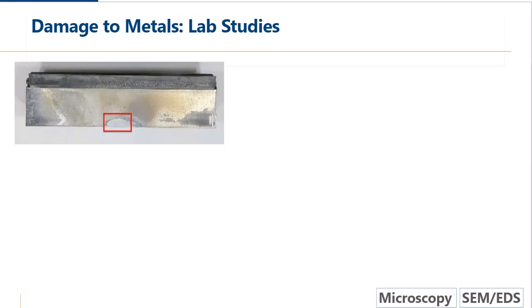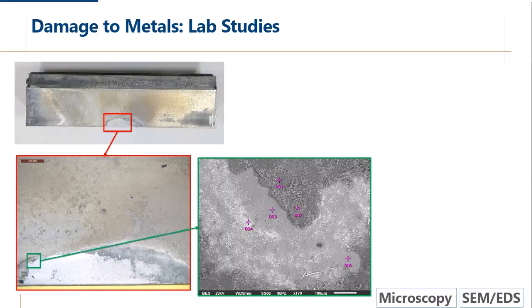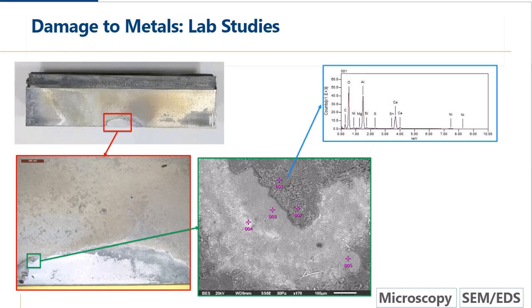So we're going to take that, look at it in the microscope, and yeah, we're seeing this sort of little half moon of silver aluminum, a little bit of brownish colored material around the edges, and this sort of thick, lighter colored stuff around the edges. So again, looking at it in greater detail and doing some elemental analysis by SEM. And again, we can see clearly there's a deposit on the surface, and there's some areas that lack this deposit. By EDS analysis, we see the deposit is primarily aluminum and oxygen. Not surprising for anodized aluminum.